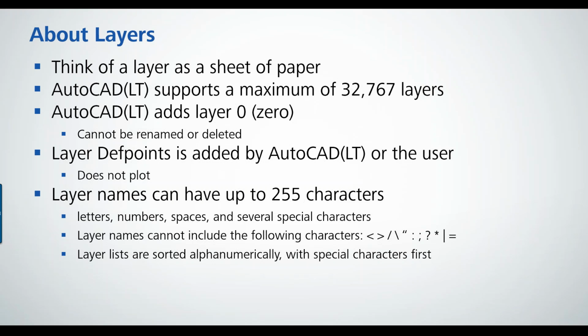So if you have a very lengthy layer name or a very lengthy drawing name that you're inserting as an external reference, and they have lengthy layer names, you could possibly exceed that limitation. I haven't seen it happen, but it could happen.